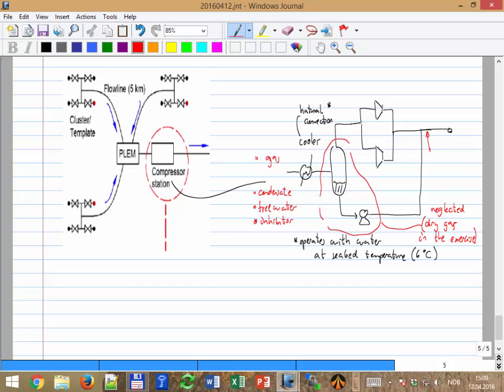Okay, so those are all the fluids that come inside. So you have to separate, compress, and then you have to join them. And there are many other things. And also there is a spare. There is another compressor typically, because if we need the two compressors to have exactly the plateau rate, and something happens in one of them, maintenance, an electrical problem, erosion, etc., we want to just close the valve. Remember, here I'm skipping all the valves, but these actually have isolation valves. So this is a spare compressor.